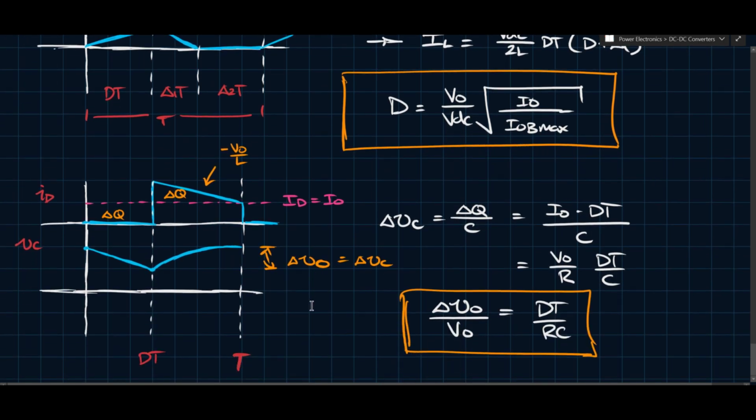And then after that, we looked at the capacitor dynamics of the whole situation, and we approached it slightly differently. We said that the area under here is the time where the capacitor will be discharging, and this is the time where the capacitor will be charging, because it's greater than the average, because the average itself would not charge anything. So it has to be that the ripple is charging and discharging the capacitor, and it's the deviation from the average that would do that, because if you just supplied a capacitor with a constant current, it would not charge or discharge.